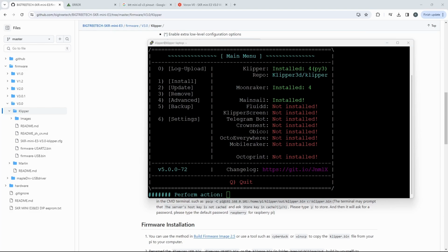All right, so I put the SD card into my main board on my Rook, and I powered it on. I gave it a couple moments, and I've plugged the USB cable into my laptop, or in your case, you might plug it into your Raspberry Pi or whichever you're using to run Klipper. So the next thing we need to do is get our ID so our Klipper machine can talk to our main board.